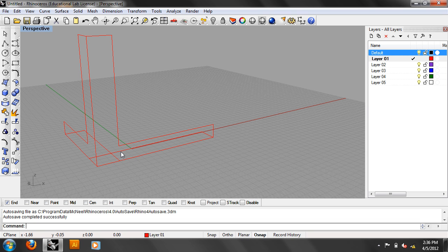So I guess then the question would be, is there not a more successful or easier way? Yeah, there's a clean way to do it, guys. If you were going to do this and not go through the rigmarole, you would take your drawings and, instead of modeling by extruding lines, draw surfaces for each of those views, make sure that those join with other surfaces, make sure that those are watertight, and then join them together.